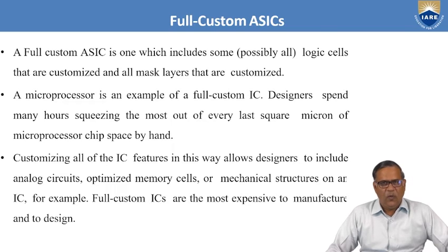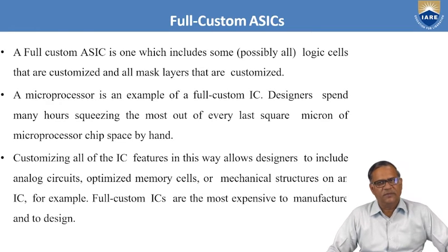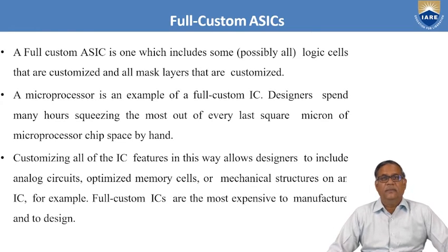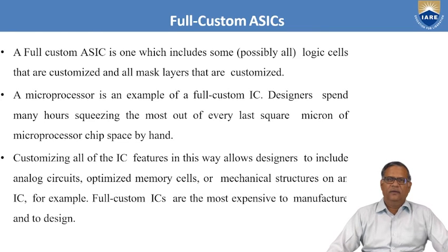Full custom ICs are the most expensive to manufacture and to design, and they take a lot of design time. So the time to market is also very high.